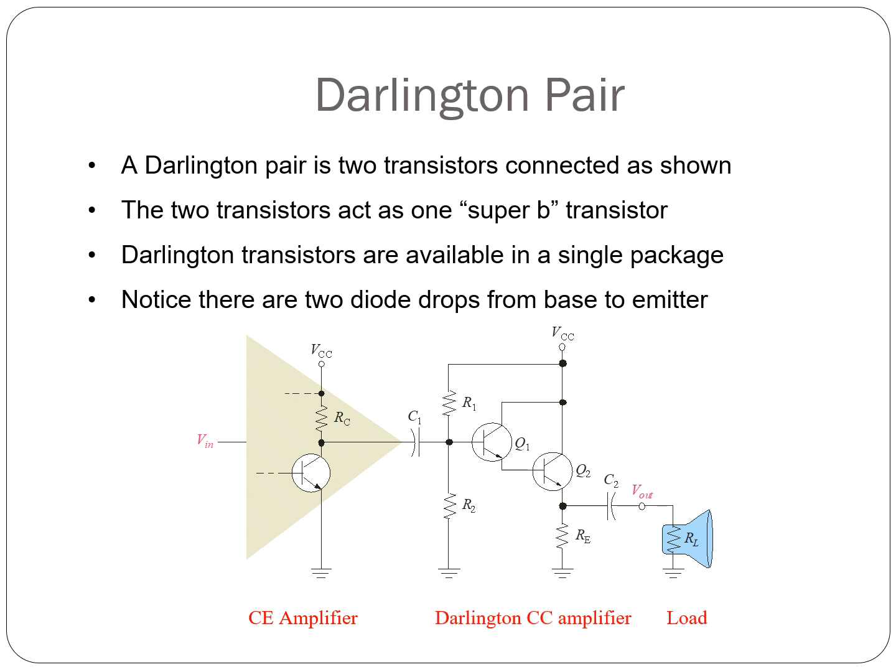Darlington pair, supercharging BJT performance. So to close out our exploration of BJT amplifiers, let's talk about a configuration that amplifies the amplifier, which is the Darlington pair. A Darlington pair is essentially two transistors connected in series, emitter to base. The output of the first transistor feeds directly into the base of the second, and together they behave like a single super beta transistor. What does all of this actually mean practically?